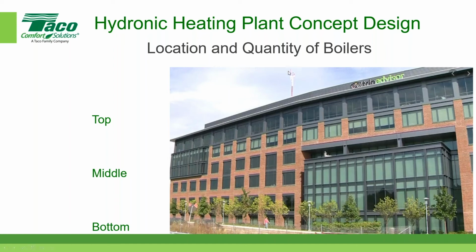Okay, so let's have a very short discussion about what we mean by top, middle, and bottom. When it comes to the top of the building, most people would put the heating plant, the hydronic heating plant, in some type of penthouse. So it sits up on the roof, and it's usually enclosed in a mechanical penthouse. Most jurisdictions, not all, but most jurisdictions will not count the height of the penthouse in the overall height of the building. So in most municipalities, the definition for high rise is somewhere between 70 to 75 feet.